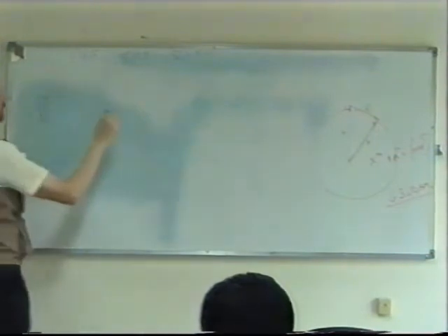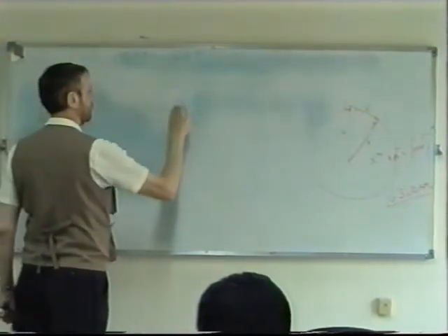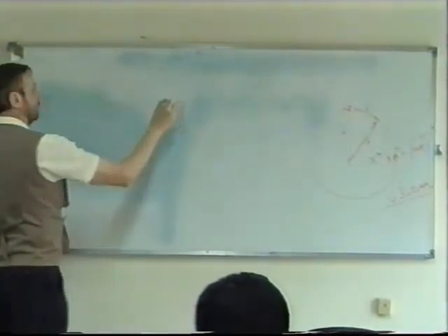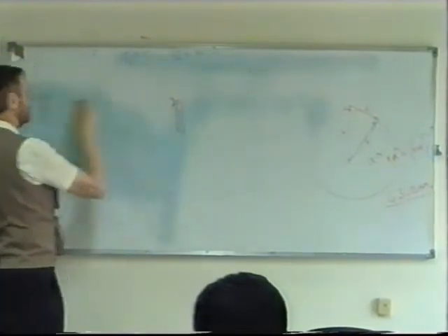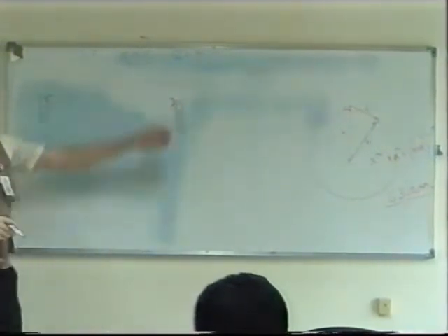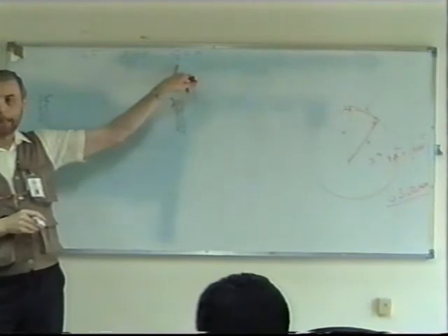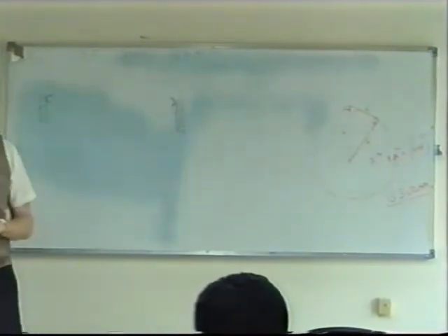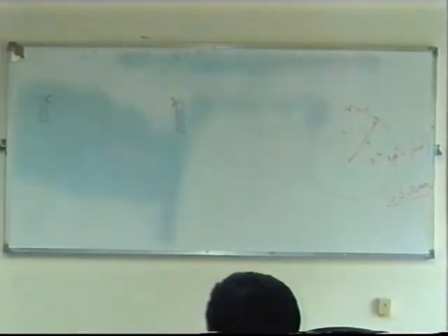So we have a point-to-point microwave dish. Now, we did say that the frequencies used by microwaves are probably in the SHF band. So what sort of wavelength are we talking about? Meters? Tenths of a meter? Centimeters, yes. We're dealing with very small wavelengths, aren't we? That's why we can use smaller dishes to get our beams between one antenna and the other.